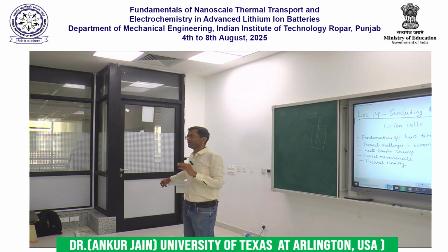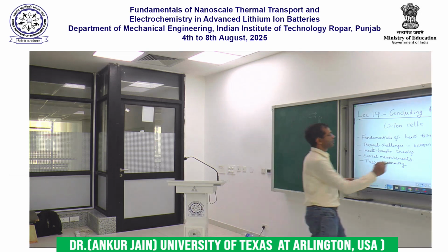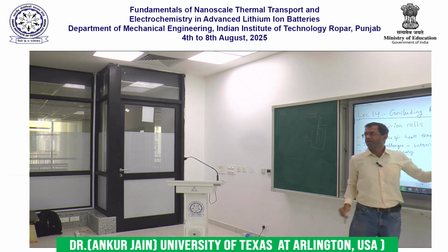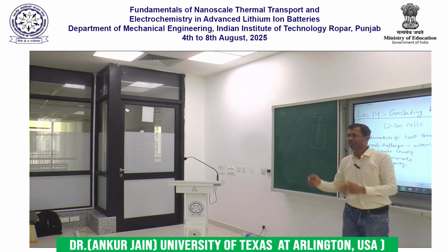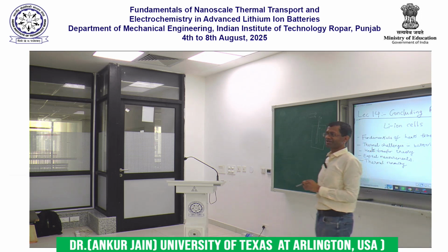There could be other systems in which there is a positive feedback loop that causes thermal instability, right? All you need is a positive connection between heat generation and temperature rise. Heat generation causes temperature rise. Is there a mechanism in the system in which temperature rise causes an increase in heat generation?